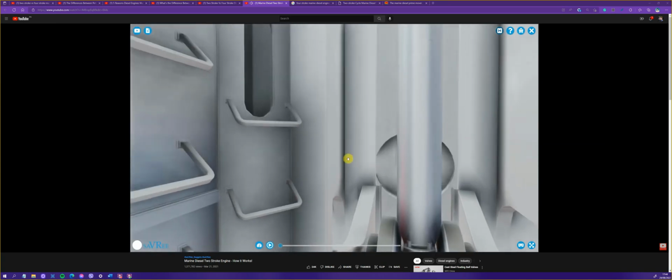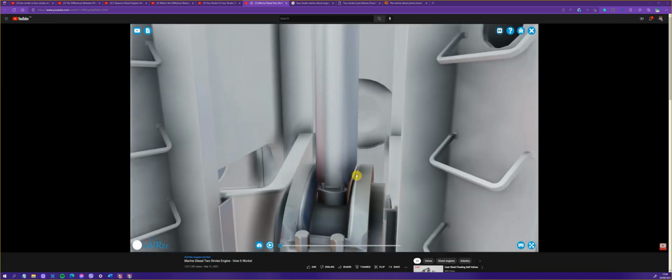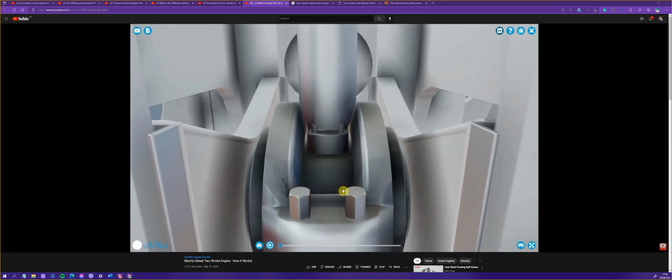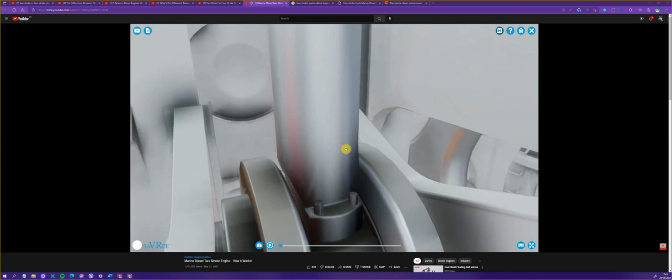Maybe you've got to disconnect. Let's just imagine for a moment we've got to disconnect the piston rod from the crosshead. So we'd need to get into this space here, and then you all stand around, hook up some hydraulic bolt tensioners, and then you have to try and undo the nuts using this hydraulic equipment, and then you can separate the piston rod from the crosshead.